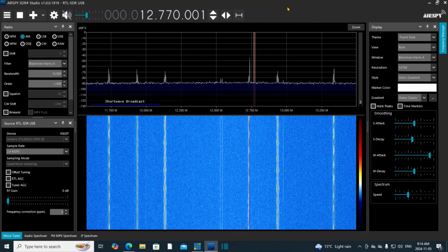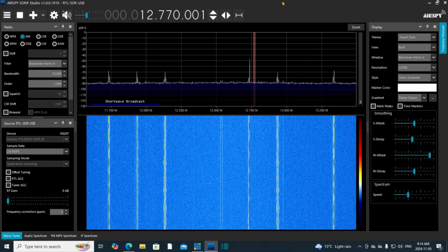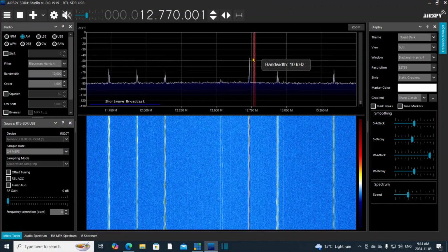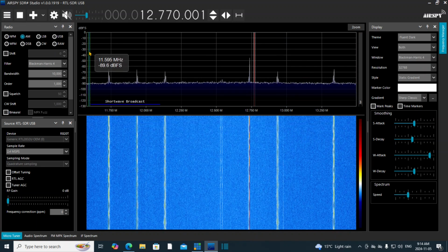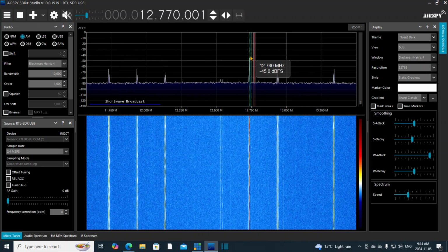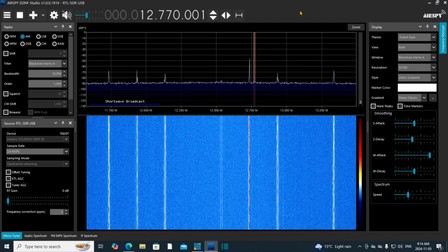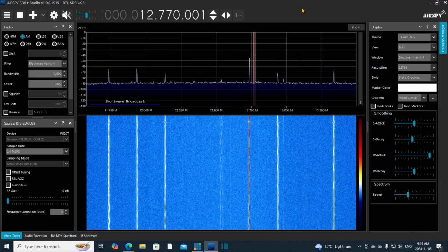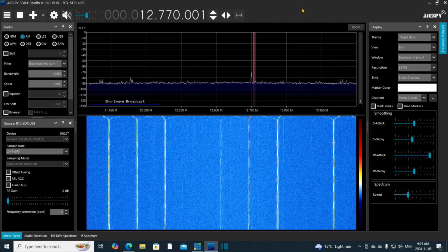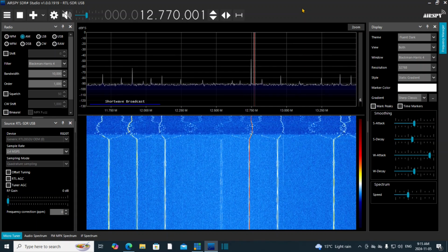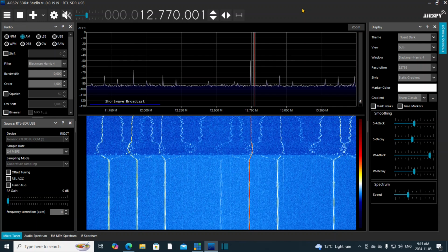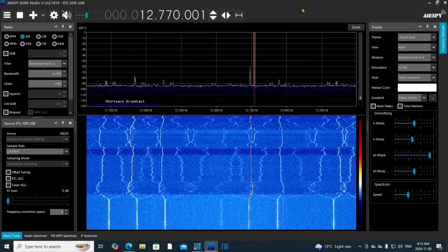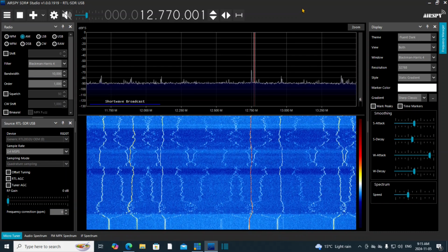Now I remember before when I did this, I got a stronger local oscillator signal on the broadcast band, but just the pickup coil was in a different place. But it was up around 30 or 35. This isn't much short of it here. And I'm sure if I move the pickup coil around, I can get more. Let's go to both ends of this band, and we'll see what the difference is in the signal strength. I'll try not to move the coil here. Let me just put something to hold it more in place.